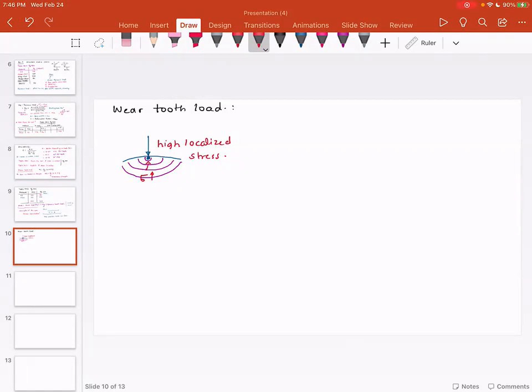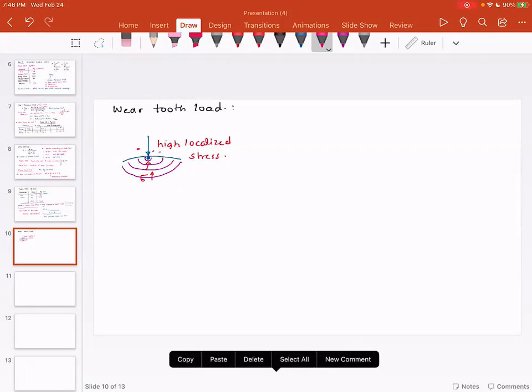But there is something interesting about this fracture. This fracture is in the form of small, microscopic elements of the material being separated. That's why, when you have gears in contact, you will notice that the surface looks either super shiny or pitted.